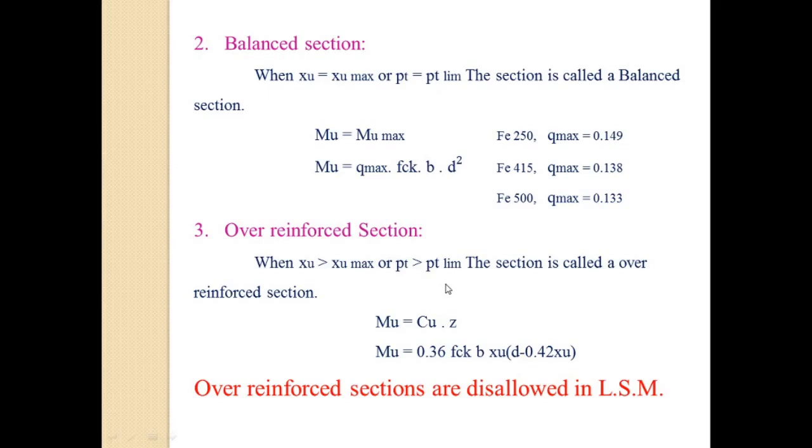Also, the moment of resistance of the section does not increase beyond that of the balanced section, even if the steel is increased compared to that of the balanced section. So that is the reason why we are avoiding these over reinforced sections.